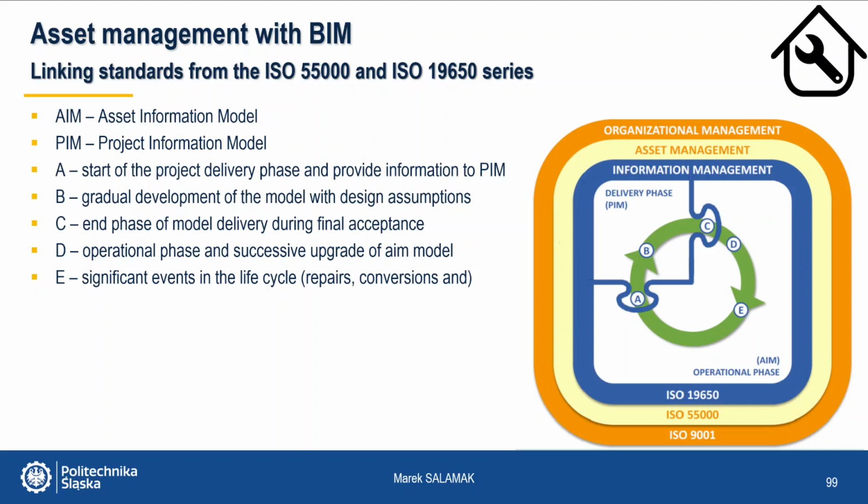Point B is a gradual development of the model with design assumptions into a virtual as-built model. Point C is the model delivery completion phase during final acceptance. It needs transfer of relevant information from the project to the asset information model. Point D is the operational phase and ongoing updating of the asset information model. And finally, point E are significant events in the life cycle, like renovations and reconstructions, that force a larger update of the asset information model.